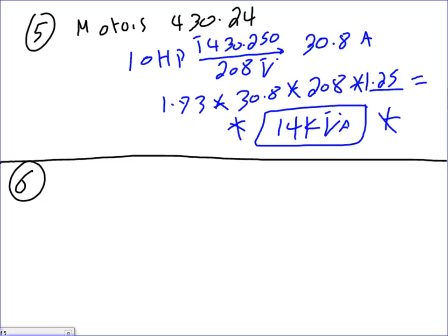That's why we run with kVA, because if we're running with kVA, it doesn't matter if the load is single phase or 3-phase when you add them all up at the end, as long as you capture it as kVA or volt-amp. Everybody knows why I have to convert everything to kVA, because kVA is voltage independent. 30 kVA 3-phase is the same as 30 kVA single phase, the same as 30 kVA 2-phase. When I say the same, you will find the current is completely different, but as a load, it's the same chunk of power.